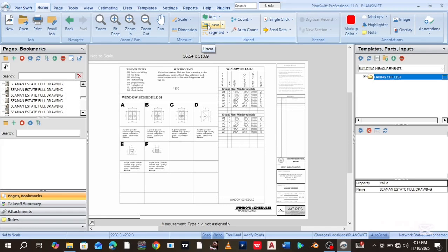So in the formula place, instead of just saying linear, you feed it a new operation: the linear meters it has calculated, multiplied by the new parameter you created, which is the height of the wall. So you can see the intricacies here.